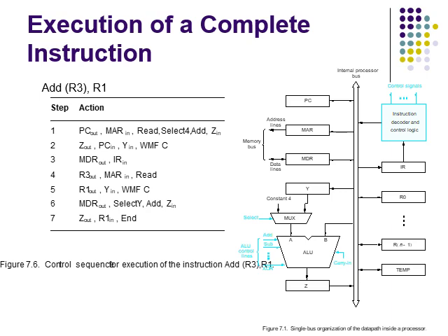In step 1, the instruction fetch operation is initiated by loading the content of the program counter into the memory address register and sending a read request to the memory. The select signal is set to select 4, which causes the multiplexer to select the constant 4.